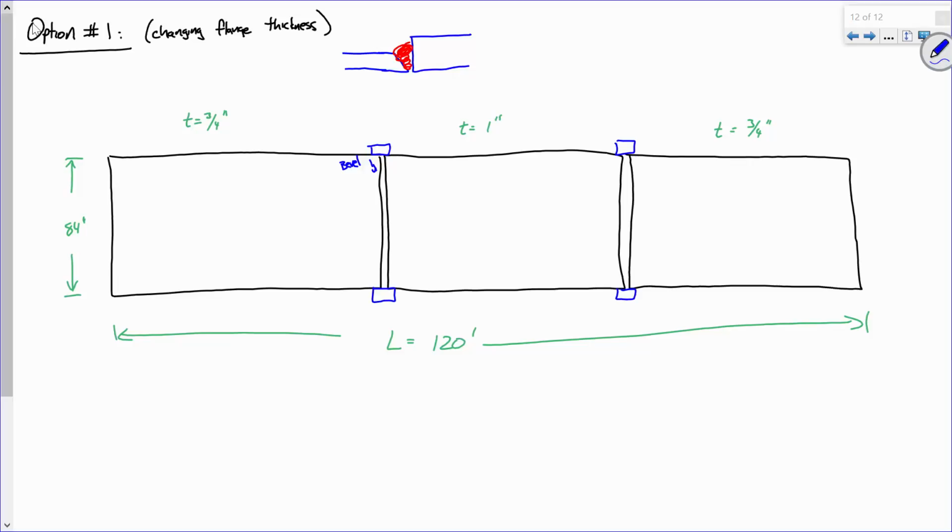I'm going to weld a little bit of steel right here and a little bit of steel right here so that when I'm welding, I can run off a little bit. You know, we're not talking about 2 feet. We're just talking about a little bit of plate right there. Sound good? So then I'm going to weld. All right, sound good? Then I'm going to get my acetylene torch out.